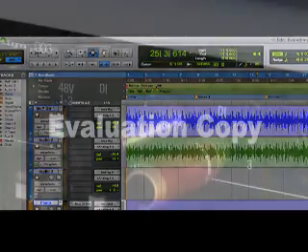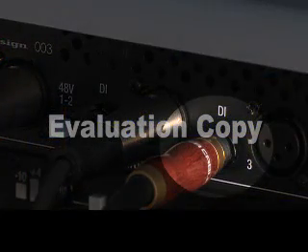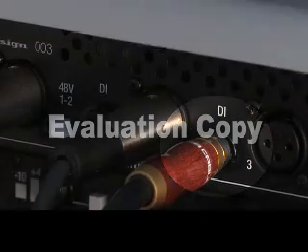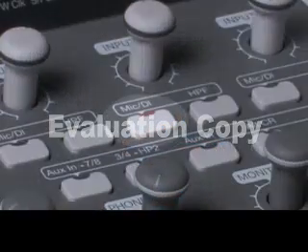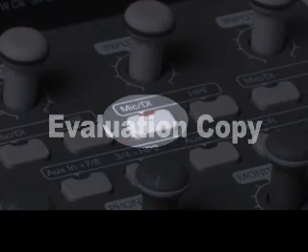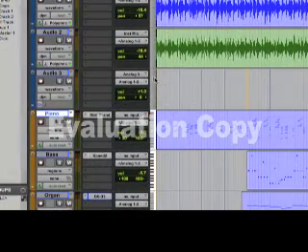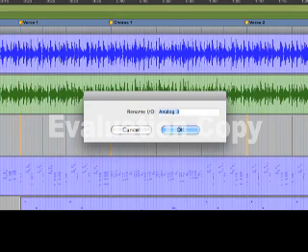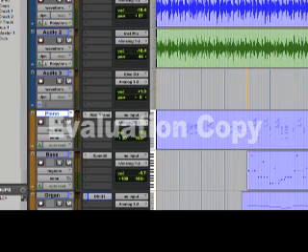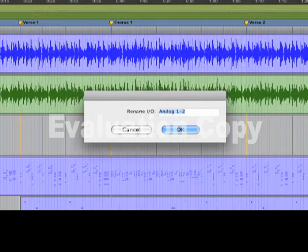Since our Anderson electric guitar is plugged into analog input 3 on the Digi 003, we'll make sure it's set to DI instead of mic. Let's also right-click again on the input and rename it Electric Guitar. And we'll rename Analog 1 and 2 to Control Room.